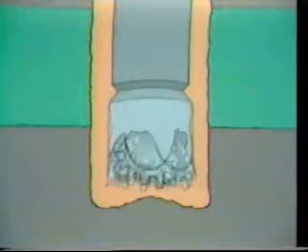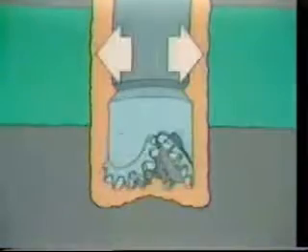As the hydrostatic pressure of the mud column causes flow into a permeable formation, the clay particles screen out on the wellbore wall, eventually forming a seal and preventing further fluid loss. If, however, an extremely permeable formation is encountered, or if the pressure of the drilling fluid is sufficient to fracture the rock,